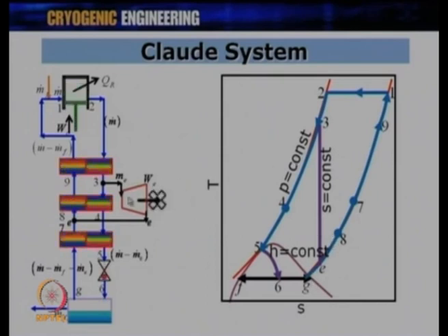Okay, coming to the high pressure line again, at point 3, the gas which is going to be here at this point is M minus Me, because Me has been diverted through the expansion engine. So, what is going ahead after point 3 is M minus Me. This gas is further pre-cooled from 3 to 4, and this is what you can see on the TS diagram. It gets pre-cooled from 3 to 4, and this 4 would match the outlet temperature of this heat exchanger, which is 7. All right. Being a 100% heat exchanger effectiveness, we can see that this point matches over here.